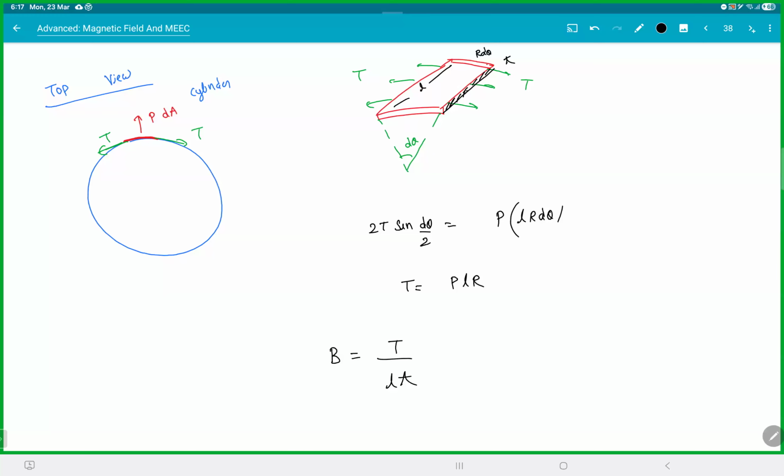So this thing, when it is trying to pop, the tension is generated tangentially. So you should take the area perpendicular to the tension. So be careful. When you took the force, pressure into area, you're talking about this area. But when you take the stress part, that is the tension into the thickness area. Are you clear with this?